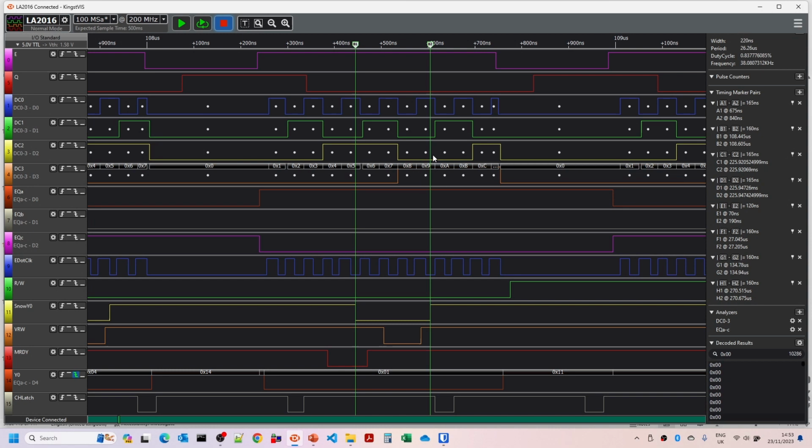I had to do quite a lot of changing around with some of the parameters for the PLD configuration to get each of the values here to fit nicely under all circumstances. Quite often it would fit for probably 80 or 90% of the signals, but occasionally you get the one outlier that would stray to overlap one of the character latch trigger points here.